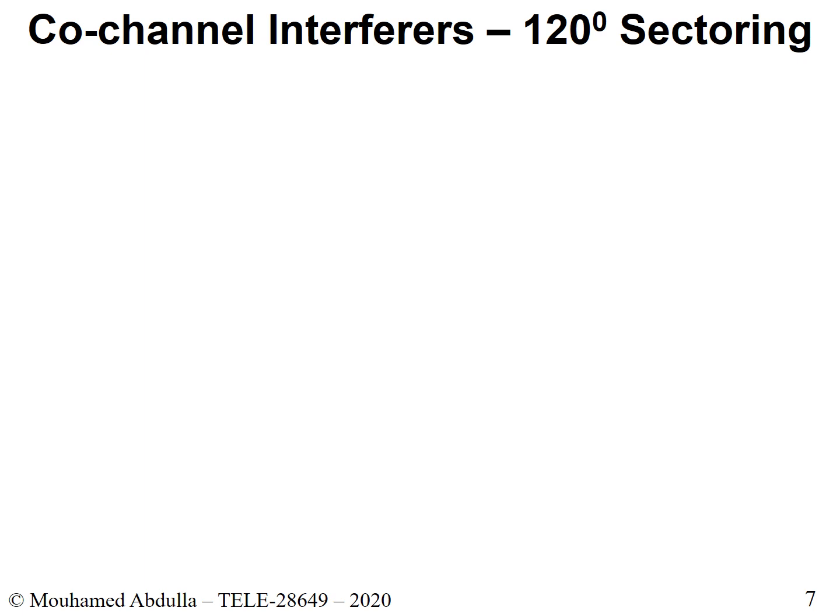But in general, if we use a hexagonal model, you'll have 6 neighboring cells, and therefore, when the antenna is omnidirectional, you'll see 6 different first-tier interferers. At this point, we're asking ourselves, well, what if we have antennas that are sectored? So they are directional antennas.